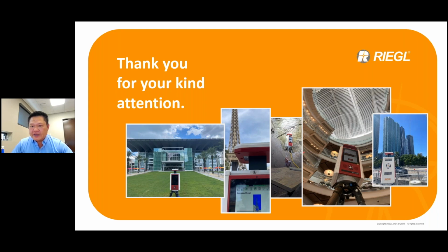All right, let me see what else. Scan time for the same setting on a 400. Okay, hopefully you forgot the i, but if you're talking about 400, 6mm resolution at 10 meters on a 600i takes 25 seconds. On a 400i it takes 45 seconds, but on a 400 it takes 3 minutes. But if you're using a 400i and you love it, upgrade to the 600i, you'll fall in love all over again. I promise you that.